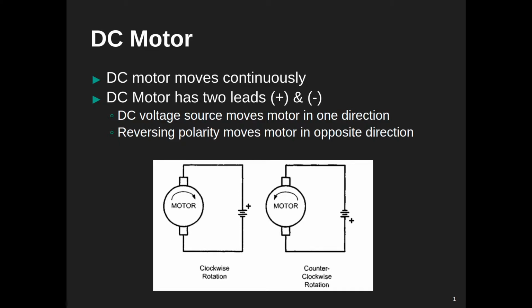Today we are going to learn how a motor driver works, how an H-bridge works, and why there's a need for them. In any application which requires a motor, motors are usually controlled by microcontrollers, and those microcontrollers cannot provide high-capacity current. The current you usually draw from a microcontroller pin is just a few milliamperes, hardly 40 milliamperes, or in some cases even 10 milliamperes.